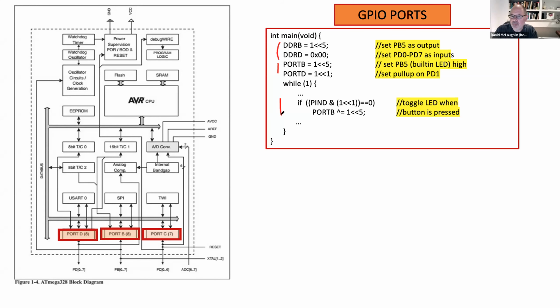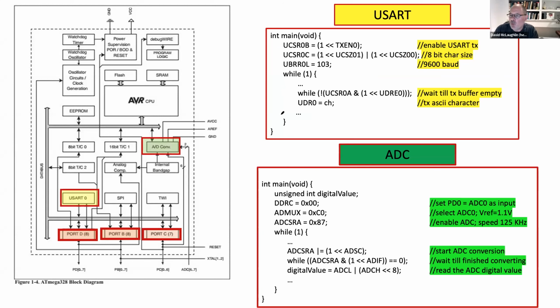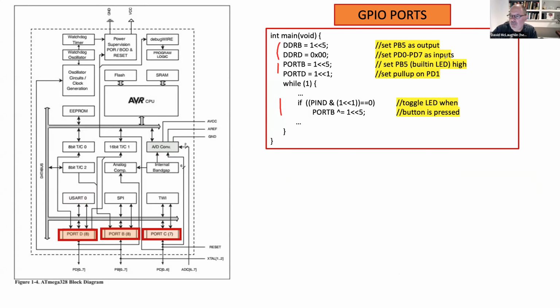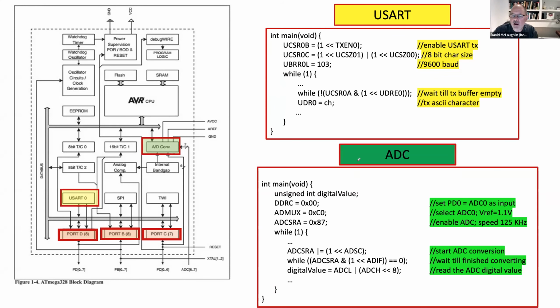Okay, so now if you remember, then there was the UART. Let me back up to the previous slide. This one, by now, I know you're all very familiar with and comfortable with, because you've been doing GPIO programming so much. When it came to UART programming, or USART, we use the terms interchangeably, you have not written much of your own code there, because I gave you some functions and said feel free to use them. You have used a function called UART init, and we have these first three functions that set up the UART a certain way. And then when you send it characters, we did this. We just took those things and tucked them away in functions.